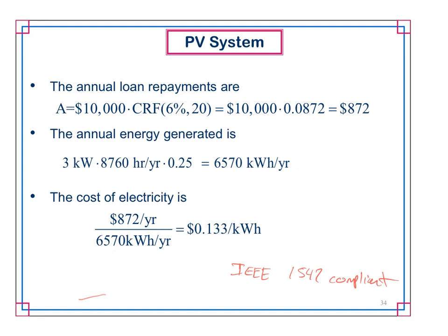So if the voltage is gone or if it's bad, the inverter will go away with it. And most of the inverters, the way they work, they're constantly trying to adjust the frequency. It's supposed to be at 60 hertz. They're trying to increase it or decrease it a little bit. If it's allowed to increase or decrease, that means the utility is gone, because you cannot change the frequency if the utility is there. So the moment you increase or decrease the frequency, then it opens up. And once you open up, you can no longer produce power, even for your home. You have to kick offline.